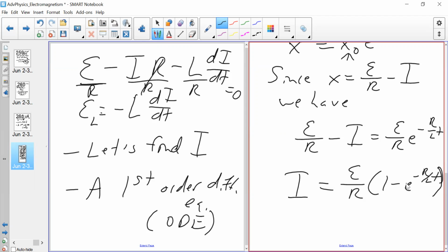But it's very similar. And so we have another time constant such that when t is equal to the time constant, we're going to get a value of this current that's 63%, just like in the charge case. When the circuit reaches its time constant, the current in this RL circuit is going to be 63% of its maximum, just like we have for the RC circuit.